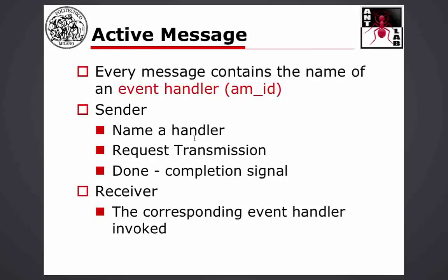Now, for the transmission process, it will be very easy. Actually, what we will do is, in the configuration file, we will specify what kind of ID we will use. Then we will use a particular command for sending a message, and an event will come back from the component when the message is transmitted, okay? So this is known as the split phase interface or split phase paradigm.